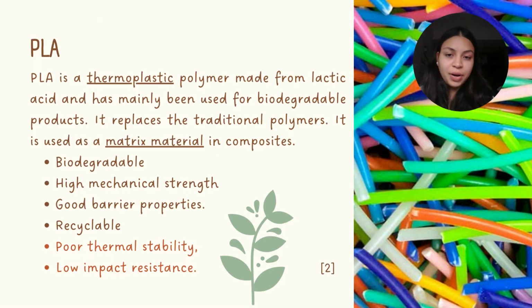For this lab practice, we use PLA, which is a thermoplastic polymer made from lactic acid, which replaces traditional polymers thanks to its biodegradable properties. And it can be used as a matrix material in composite materials. It has great properties such as its high mechanical strength, that it's biodegradable, it has good barrier properties, it's recyclable, but it also has some inconvenience, which are its poor thermal stability and its low impact resistance.